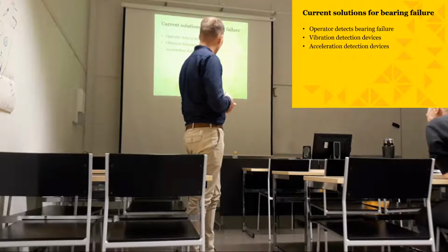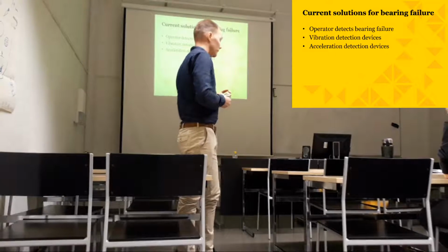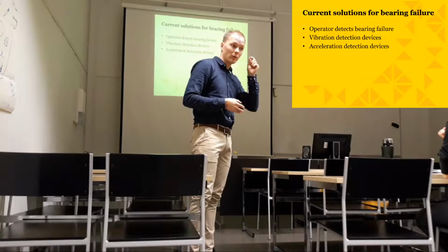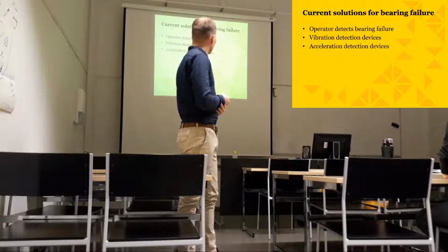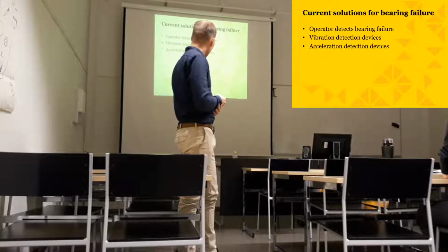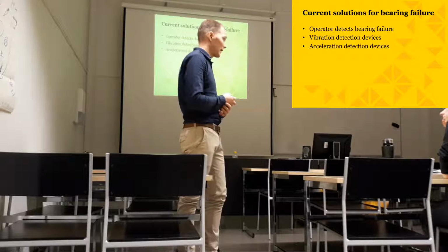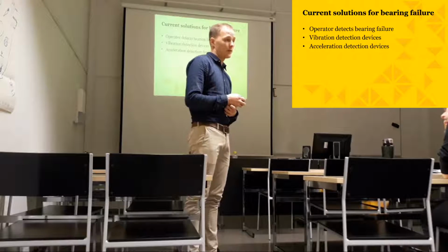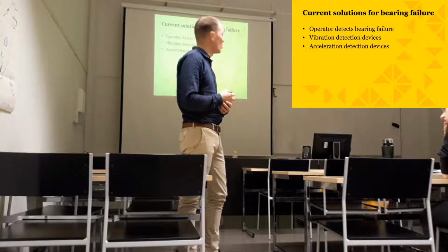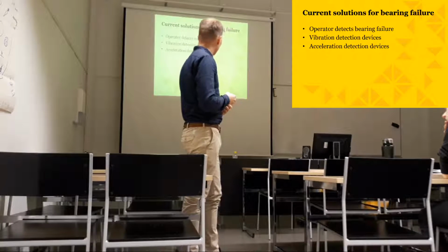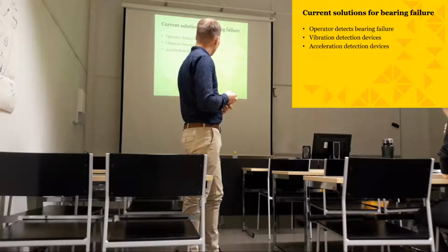Here are the current solutions for detecting this kind of bearing failure. The operator basically hears it when he walks in the plant: okay, this motor makes a funny noise. There are also vibration and acceleration based methods, and these are already products used in the industry.